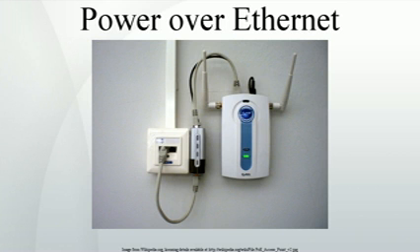The updated IEEE 802.3at-2009 PoE standard, also known as PoE Plus or PoE+, provides up to 25.5 W of power. The 2009 standard prohibits a powered device from using all 4 pairs for power. Some vendors have announced products that claim to be compatible with the 802.3at standard and offer up to 51 W of power over a single cable by utilizing all 4 pairs in the Category 5 cable. Both of these amendments have since been incorporated into the IEEE 802.3-2012 publication.